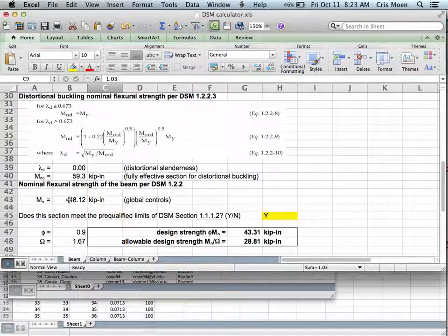Are there any questions? Yes. I would just try to get close to where I was supposed to be, and I would put the braces at the quarter points of the span if I had rigid board.